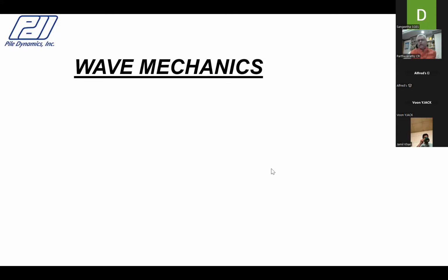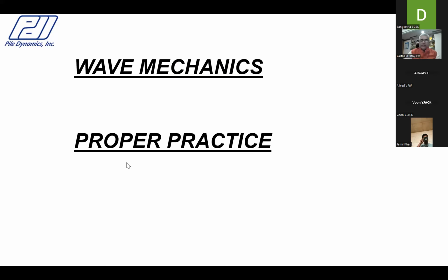So for both this pile integrity test and the high strain dynamic test, you need to understand one-dimensional wave propagation theory. It's common for both. Proper practice, how to do the test right in the first place, what are the precautions to be taken, how to instrument the pile, how to get the data, how to make an assessment of quality of the data, the application and the interpretation of data sets. And finally, for the high strain dynamic test, we have to analyze and understand about the CAPWAP wave analysis program. These are part of the training we conduct. So Sangeetha will give you more details towards the end of this presentation.